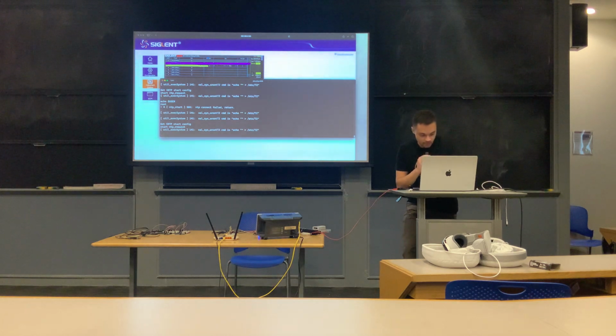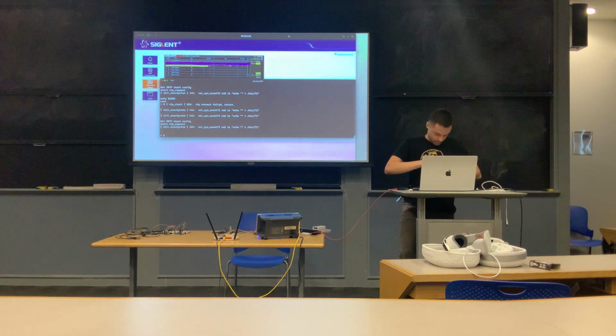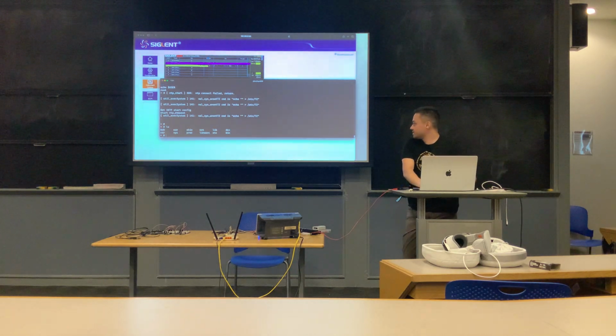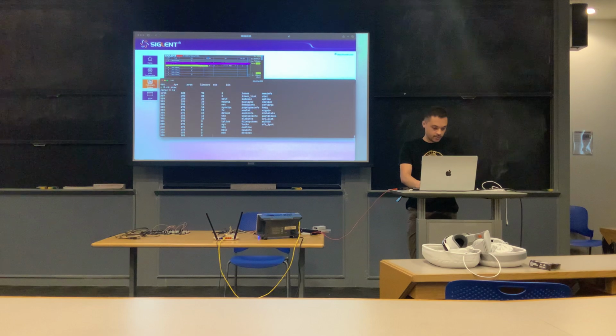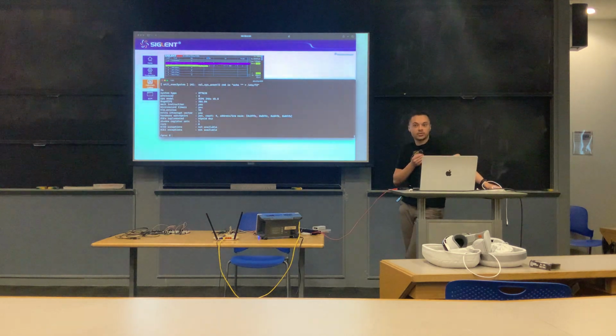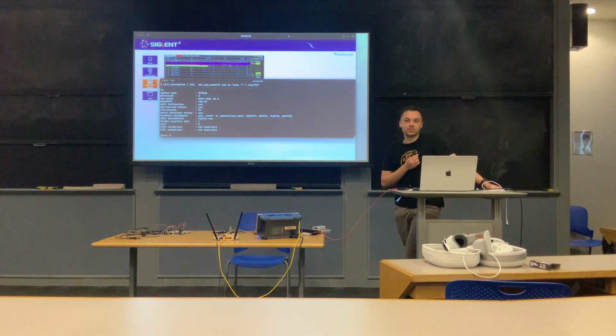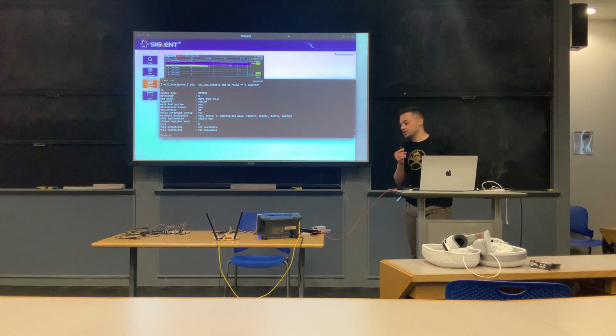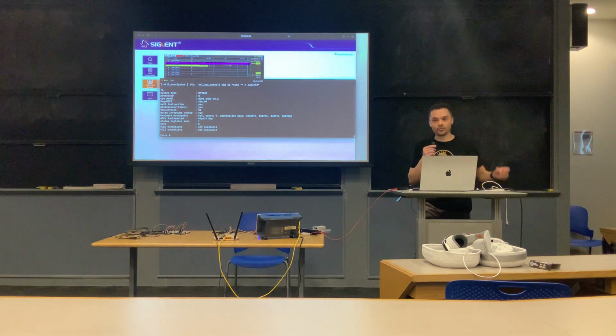So let's see what else we can do. If we pop into here, we can actually ls, and oh, it's a Linux system. We can go into proc, and we can see we run a MIPS processor. We can use cpuinfo. You guys should be familiar with that from the labs. And you can see we're totally root on this Linux system. So we have complete ownership of this router just by plugging into some pins that were already on the router.